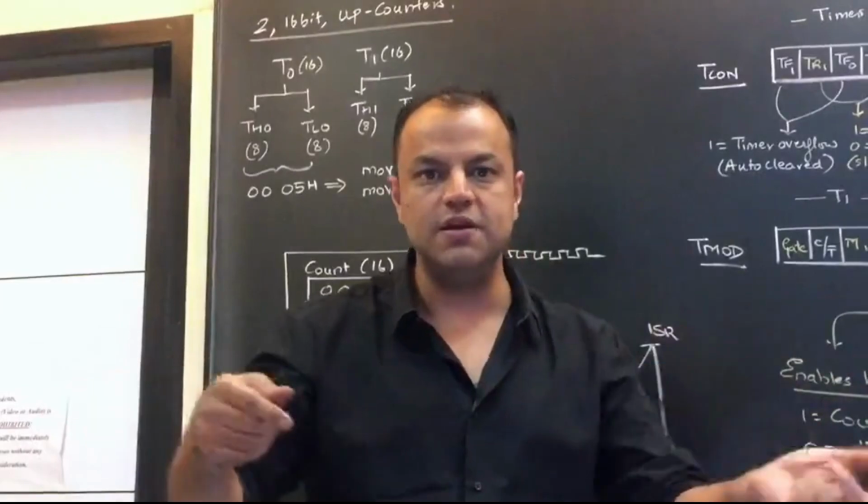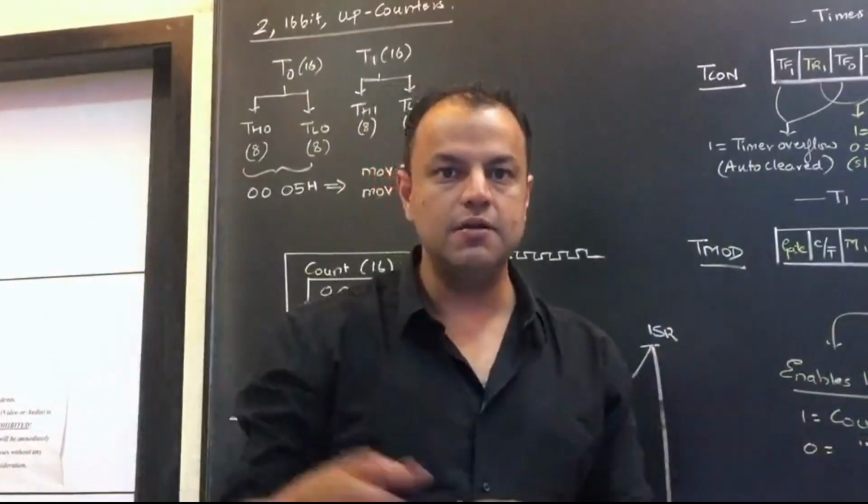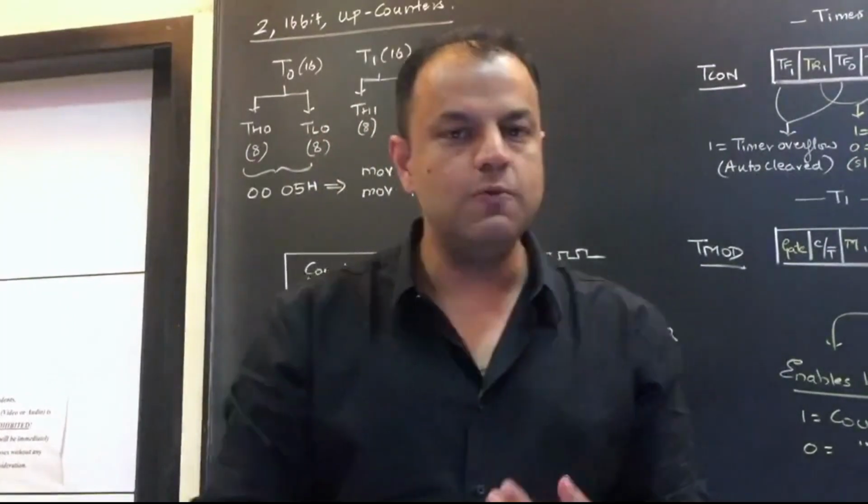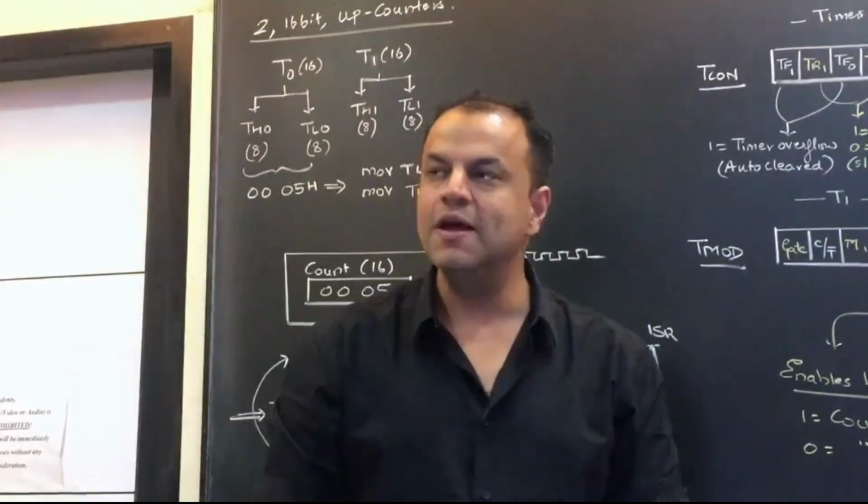Now if I have only one timer, that means I have to wait for one delay to get over to start the next delay. But if I have two timers, I can simultaneously engage another timer, you produce another delay. Both timers are producing delays, and the processor is free to do another operation. Whichever timer finishes the delay will tell the processor and it will do the appropriate action. Tell me, did you understand? So what is better? Having one timer or two timers? Of course, two timers.